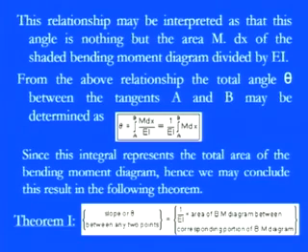What we have is the integration of M dx. Now this M dx will always give you the area under that particular portion. These deflections are coming due to the bending moment, and they vary with the dx distance. So M into dx will give you the area under that curve. Just like you focus on the work done.